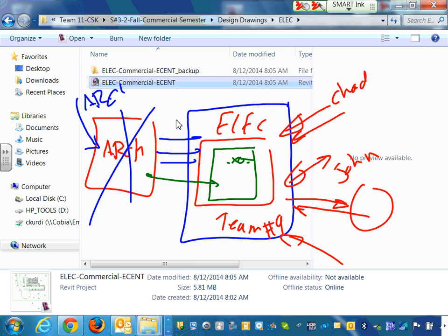But he has to push his stuff up for you to see it, and vice versa. At the moment he does sync his stuff, a notice will pop up in Revit. Absolutely, you have to reload though. When he pushes his stuff in Revit, you have to either sync or reload latest to see his stuff.